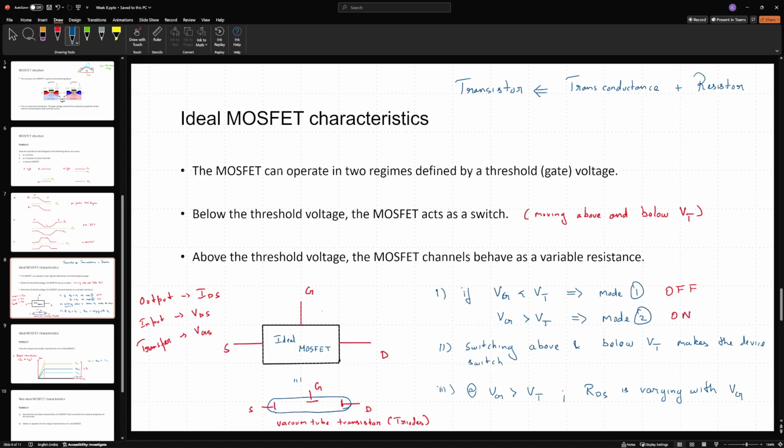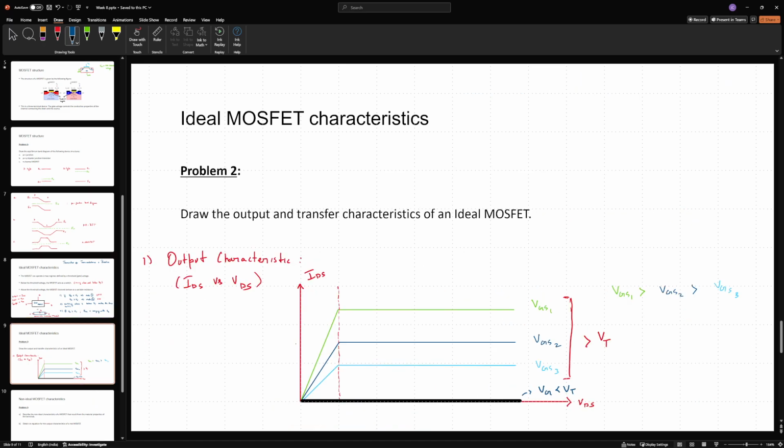Now, why is saturation a thing? Let us think about it from the ideal standpoint itself. Ideally, why do I want my device to saturate? Why don't I expect that the resistance just keeps on increasing? Why do I even desire a saturation? Imagine if I didn't want saturation, and these lines all just extended like this all across, then would I have a transistor? The answer is no. In that case, I will have just a rheostat, a variable resistance. I can just use some external device to modulate that resistance.